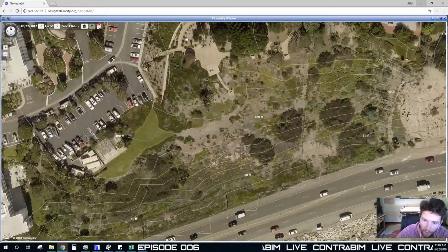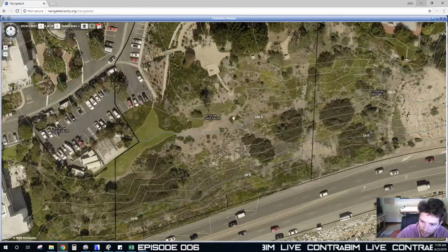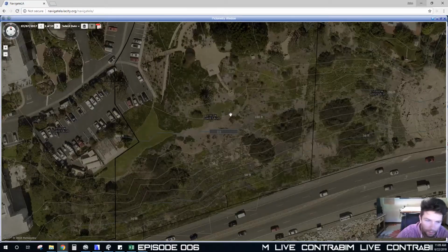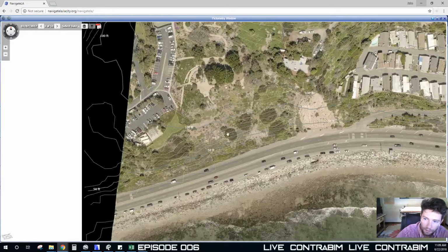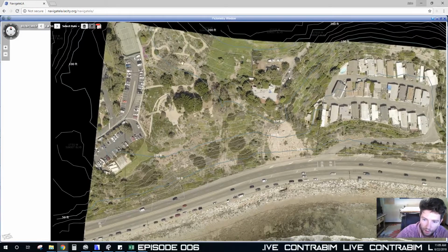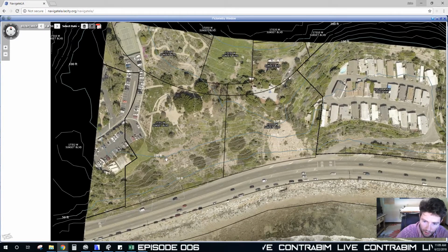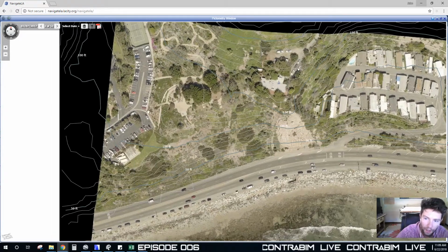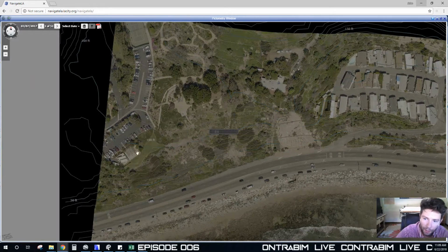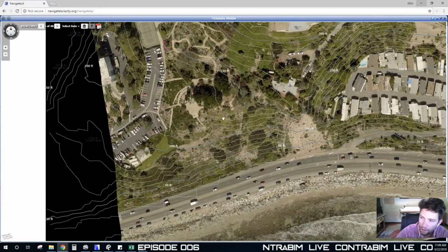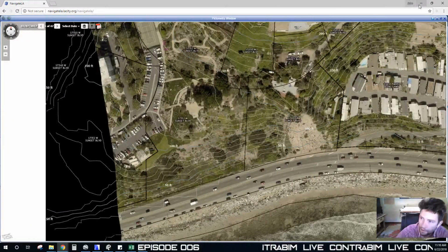And I'm happy to be able to use a source like this that's available for free and something that we can actually do a lot with. So if I really wanted to get super tight on the tolerances of the excavation, I'd hopefully try to get down to at least every 5 feet or every individual foot increment for my topo lines. But at this stage, for what we're looking at today, we definitely do not need that level of detail.